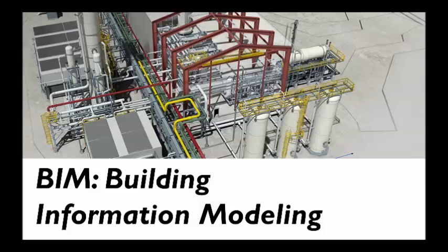Now there are still some 3-dimensional objects in CAD, but what BIM does is it allows you to put actual building information embedded into the object so that you can get more accurate material information, manufacturing information, and construction detailing. It more closely interfaces with your construction documents and the construction process, and all the systems involved in the building, more closely mimicking and modeling what it's going to be like in reality once it gets built.